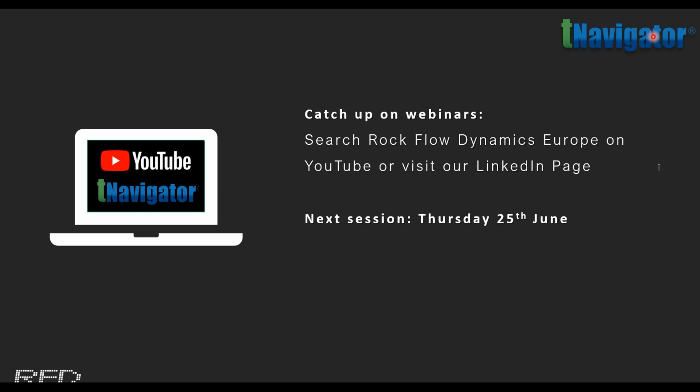Let's go for the first question: how do you handle very thin deterministic beds from isocores? Do the bed thicknesses translate across into 3D, especially near the faults where interpolation exists? In T Navigator, in the 3D modeling, you have the control to set the minimum thickness of layering. But if you have thin deterministic beds from isocores, you really have to make sure they are properly captured in your 3D model building. So we can do that, but you have to pay very close attention.